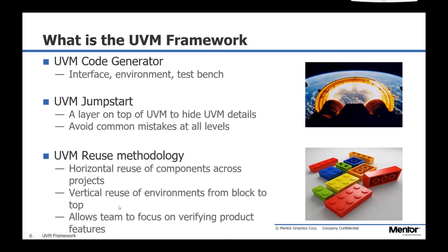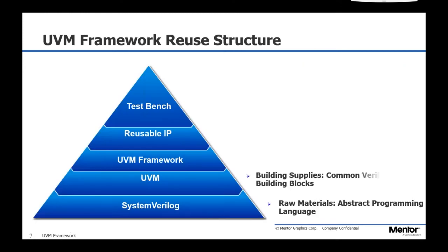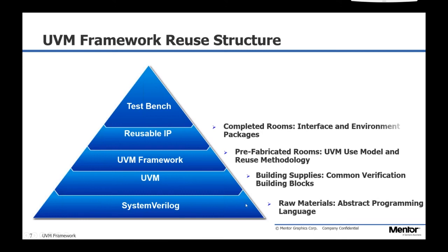So it's really meant to be a jumpstart, and it's meant to be a methodology where we've really thought through a lot of the pitfalls that new users end up facing the first time they're doing a UVM environment. If you think about SystemVerilog, it's the enabler, the tools, the raw materials that are allowing you to do this. UVM is the next level up. It is, let's put some structure around that code. Let's give you the framework to build your house, say.